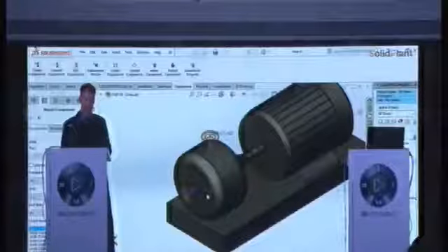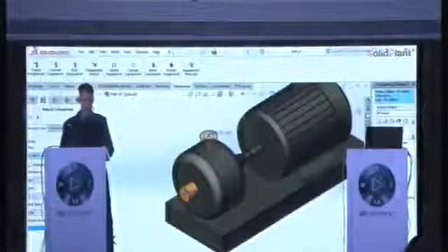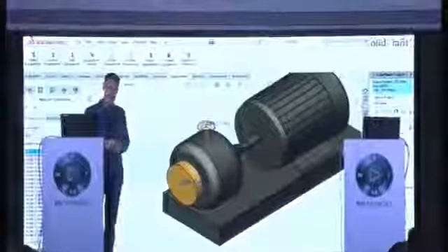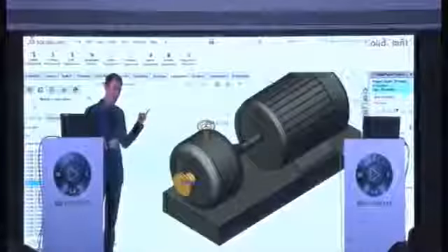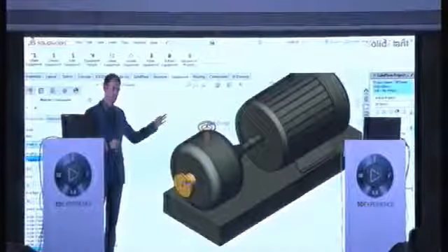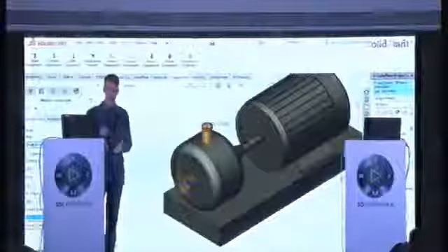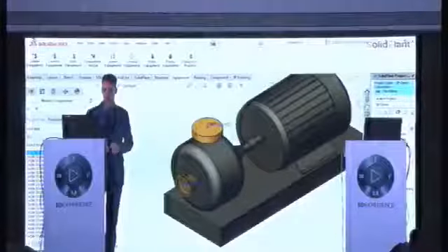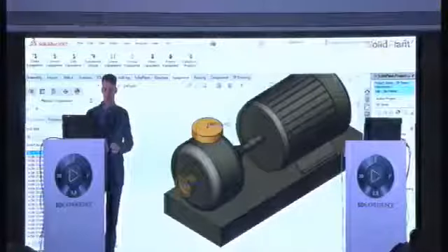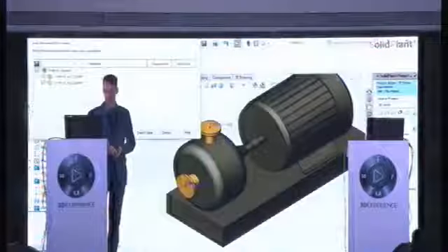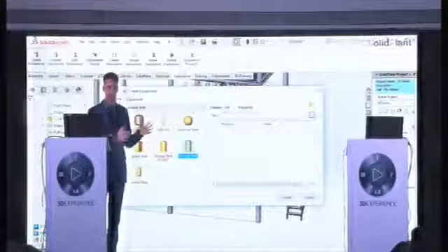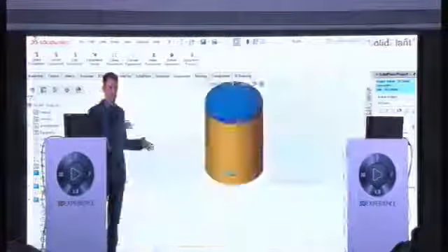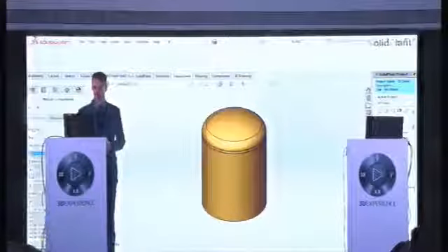Here is where you enter all your variables, and from there you can assign your tags. Now, all these tags are actually coming from our P&ID solution. We can synchronize the data from our P&ID into 3D, so all the data for these tags and nozzles is already there. All you have to do is select them from your list and assign them to this pump. The data from your P&ID will stay the same in your 3D solution without having to enter all the data again and again. It's already there.